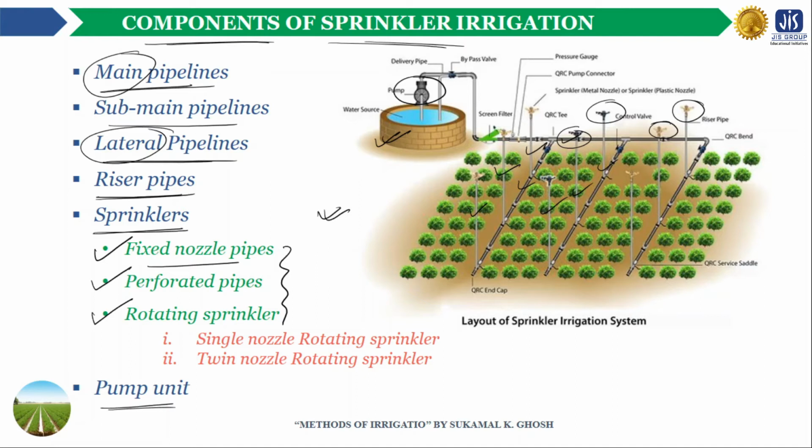A series of such pipes are installed parallel to each other at a distance of about 15 meters apart and are supported on rows of posts. The spray of water is developed through the nozzles, and the entire 15 meters width between the pipelines may be irrigated by turning the pipes through 135 degrees.